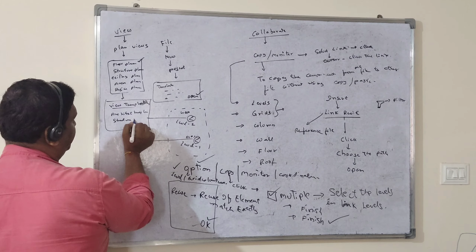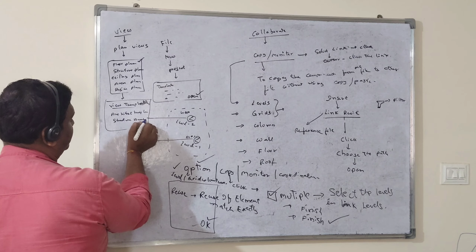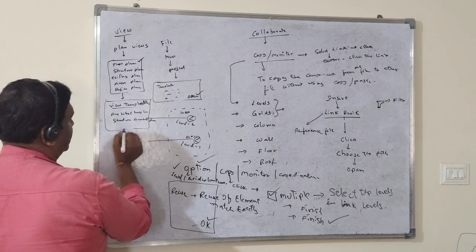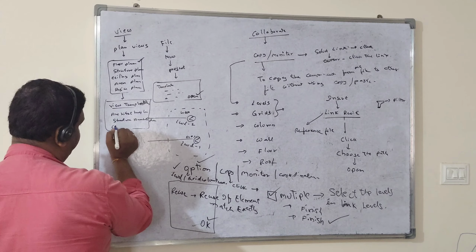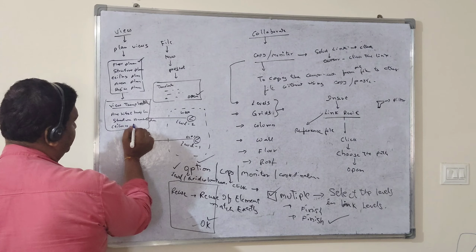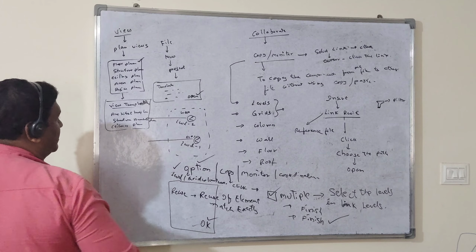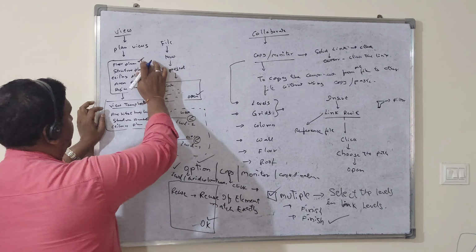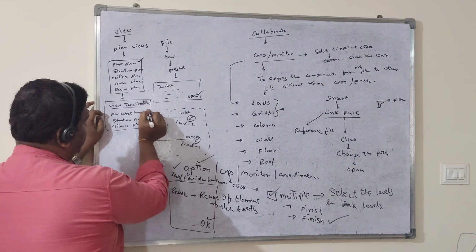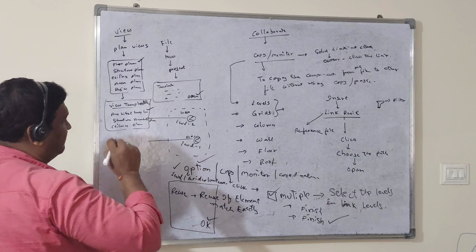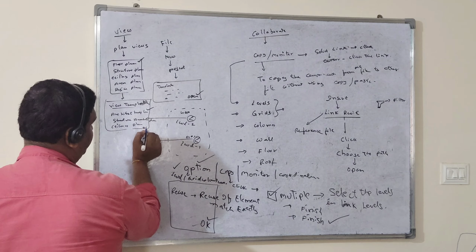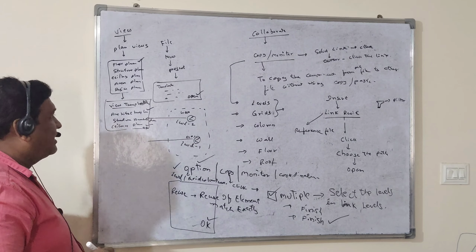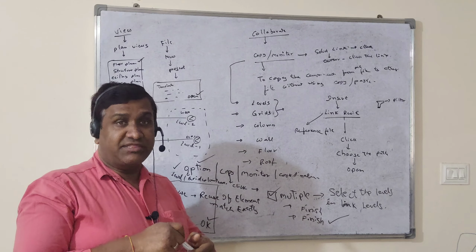Structure means structure, foundation or framing, whatever you require you can go with that. And there is also a ceiling plan template. Like that, whichever template you require. Right now we have selected floor plan, so you have to go to architecture floor plan. If you click it and go with the tick mark here, that template has been selected.